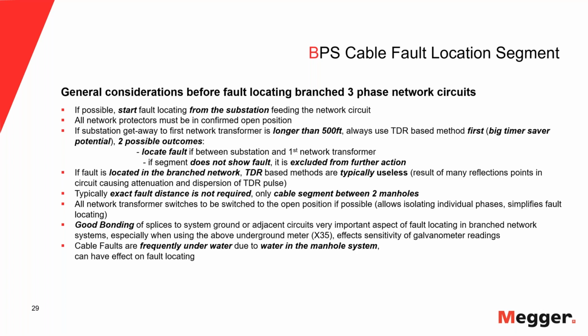Another thing that's very important: all network protectors must be open, must be confirmed open, because I cannot have feedback from network transformers into the circuit I want to fault locate. Most of the time today that is done via SCADA operations. In the old days, one had to go out to every transformer and make sure that the network protector actually opened.